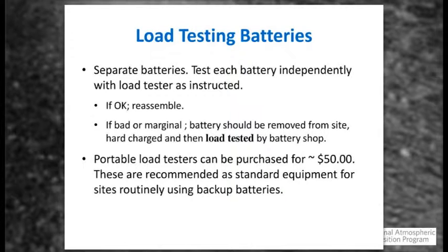Load testing the batteries. This is important for ongoing site maintenance. You do need to disconnect each battery independently. If you have them wired in parallel, as we talked about, you could disconnect one and leave the others connected to the equipment, but you do need to independently load test them. You don't want to do load testing across the entire bank. You want to do it on each individual battery.